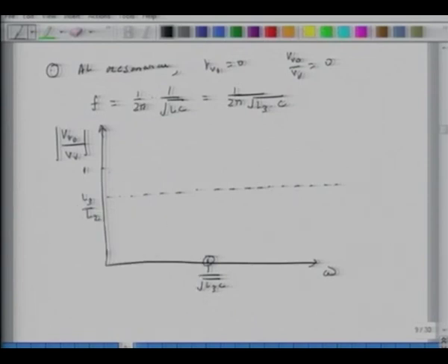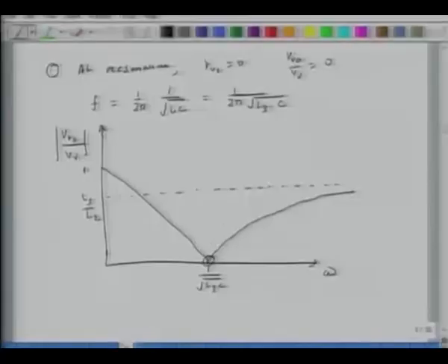So my transfer function will look something like this. In all other examples of the resonator, I was using the resonator to boost the performance at specific frequencies. Here I am using the same device to kill specific frequencies. In this case, something in this band, I am able to attenuate the magnitude of that.